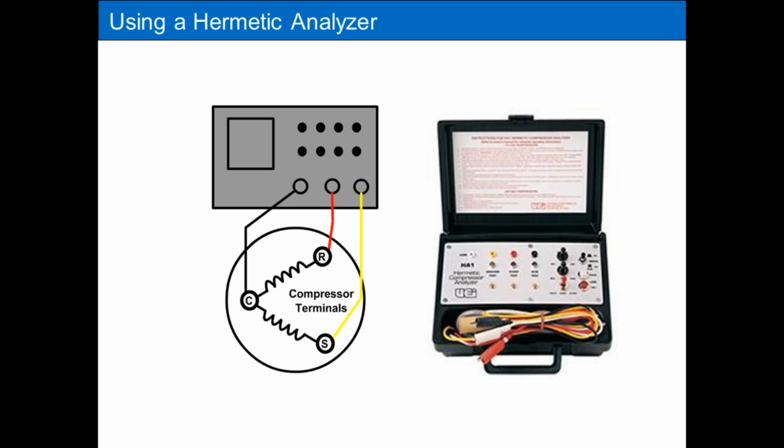So when in doubt, go to a hermetic analyzer. It's a worthwhile tool to have. It really allows you to be real confident knowing that the compressor is electrically good or not, or turns over or doesn't turn over.